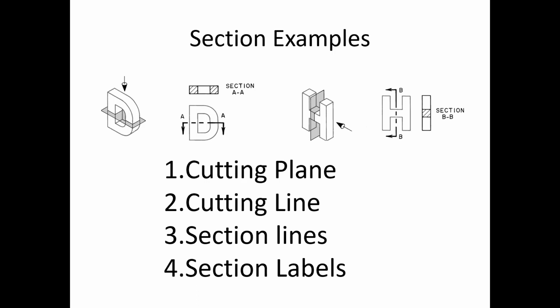Don't start with C. Later on, when you start drawing in Inventor, if you make a section view and you think, oh crap, I didn't like that one, and you erase it and start all over, the next one you make is going to be B. And A is not going to be on your drawing anymore, but you can change it. Just be aware of that. It's going to advance as you make multiple section views, even if you erased them. So you have to go back and correct that. You can correct it, and it corrects fine, but just be aware of that.